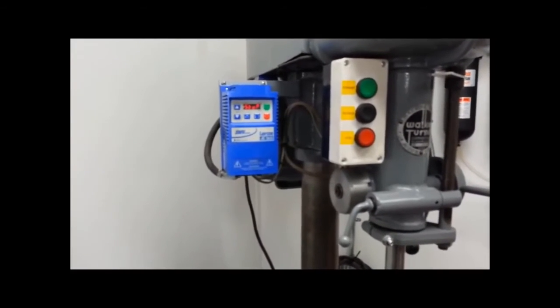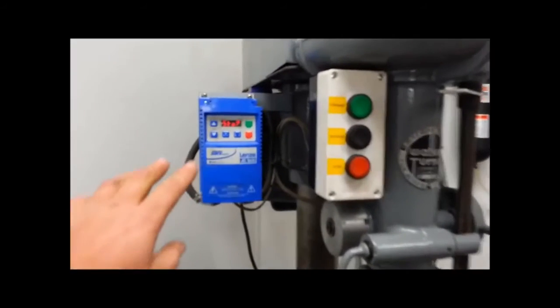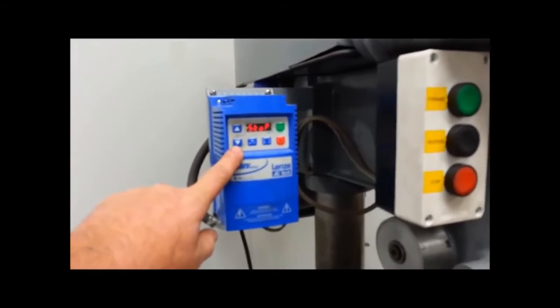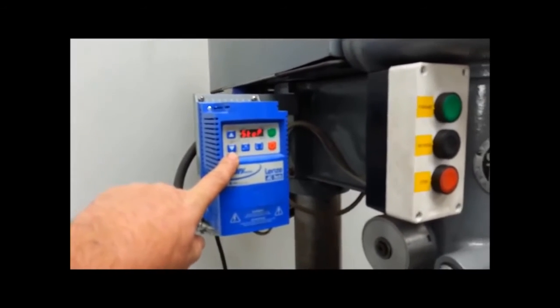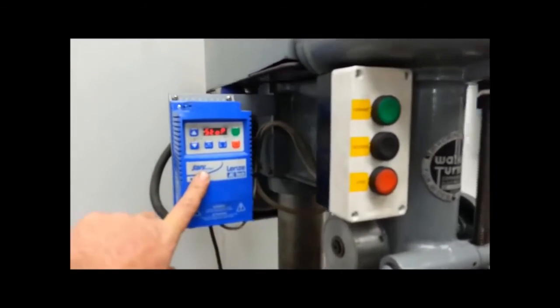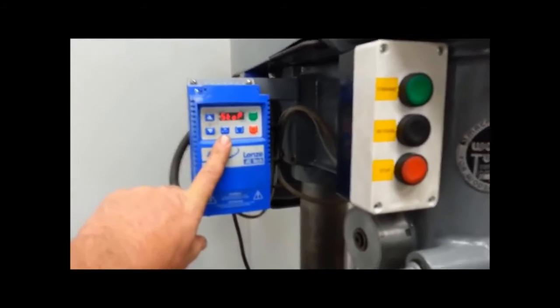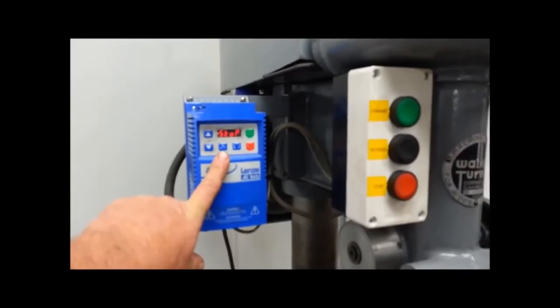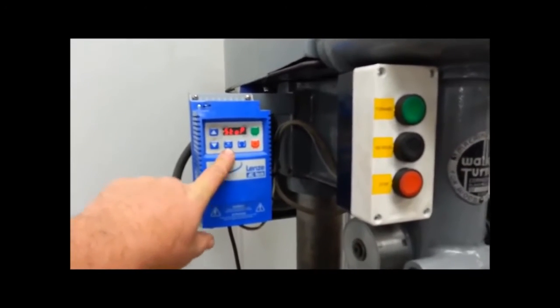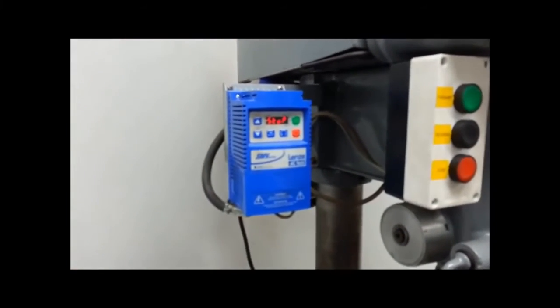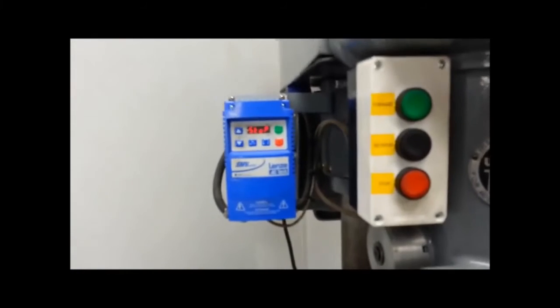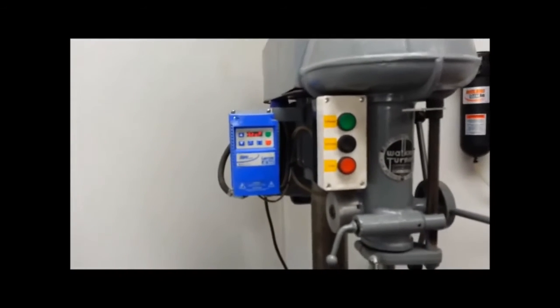And that is the point where your VFD needs to be programmed to go into alarm and lock out, or trip a breaker, or trip an overload block, or whatever. These are programmable for running protection for your service factor amps. So you program into these the ragged edge, right where they're going to trip, and that's all done off your motor data plates.